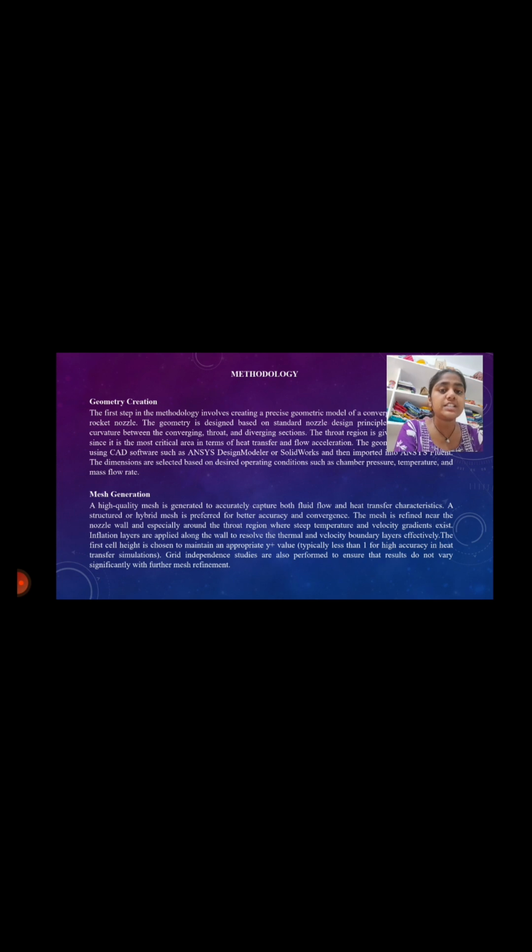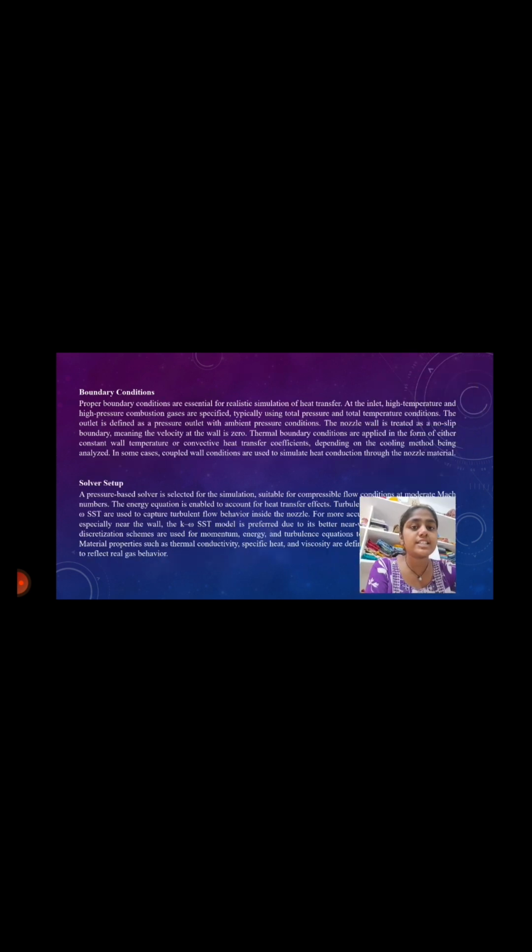The first cell height is chosen to maintain an appropriate Y plus value, typically less than 1, for high accuracy in heat transfer simulations. Grid independent studies are also performed to ensure that results do not vary significantly with further mesh refinement.